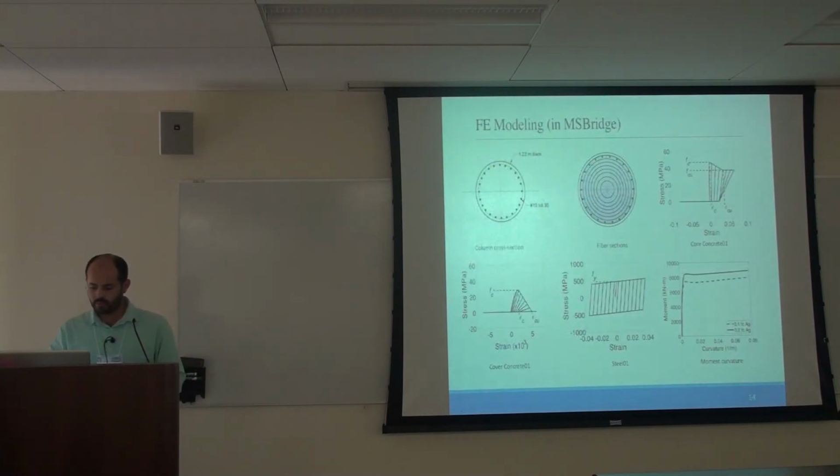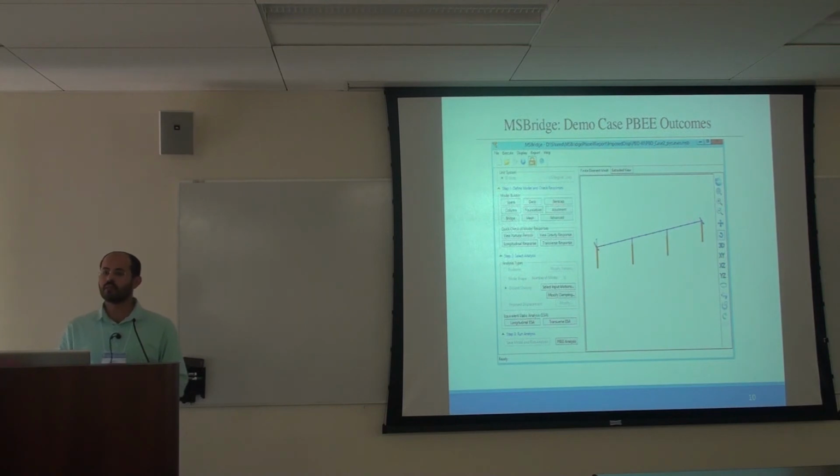Maybe in the video it was part of that. Let's say I create a model of maybe a building, and I have multiple Tcl files. Can I just tell the program, okay, this is the file I will start running the model with? Can it go through each of the files or no? If you have a specific component, then yeah, you can feed it the Tcl file. But you have everything from scratch. Whenever you have this input file and you run it, you can see all the files. You can get to any file and change it according to your knowledge of OpenSees. You can do that, but something from scratch, and especially not a bridge, no, it's not working like this. It needs more work.